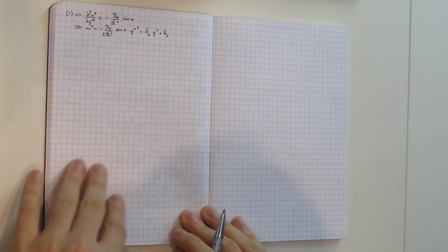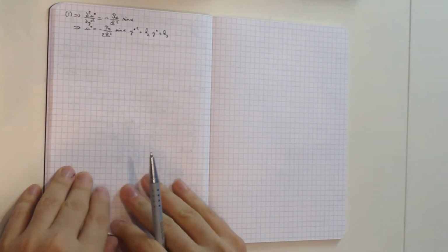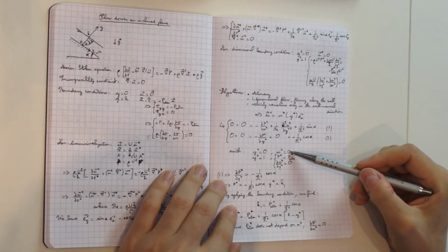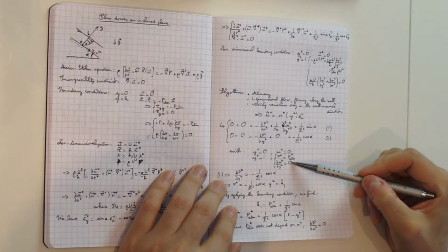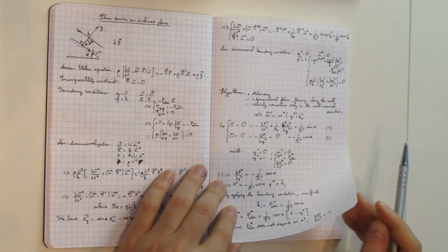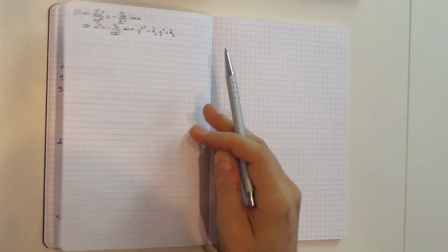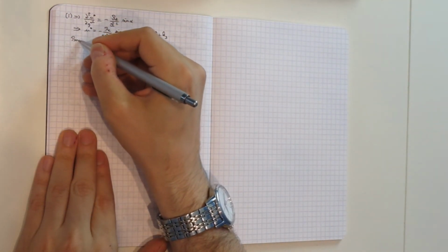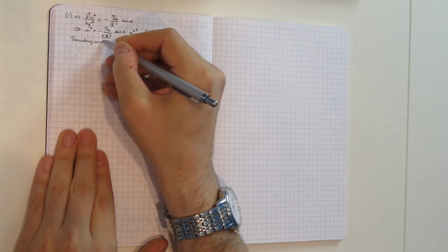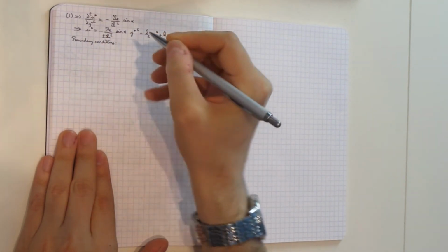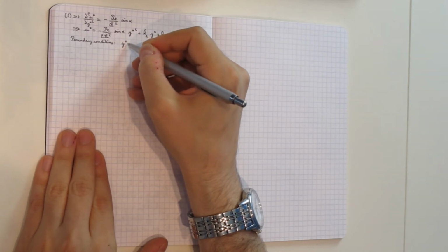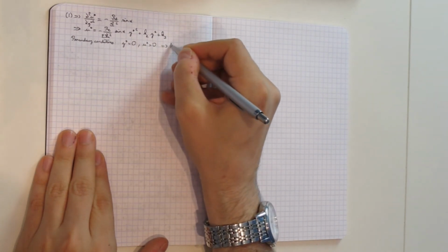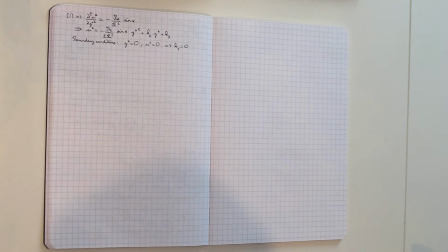And so here we have boundary conditions to apply. Of course, we have two constants of integration, so we should have two boundary conditions to apply. We have one boundary condition at y equals 0, which is the velocity has to vanish, and the second boundary condition is this no stress boundary condition at the free surface. So applying the boundary condition u equals 0 at y equals 0 leads us to say that K3 equals 0, okay?